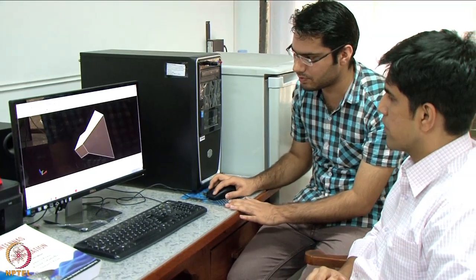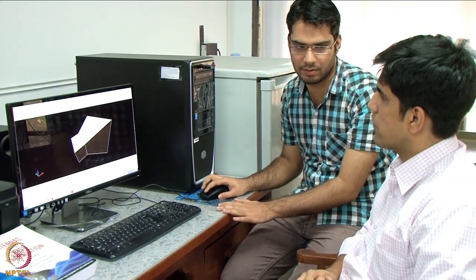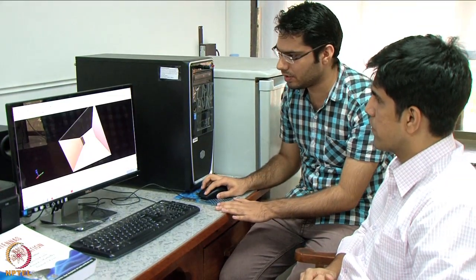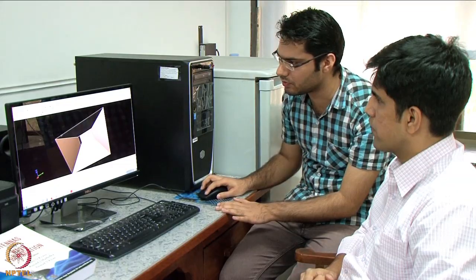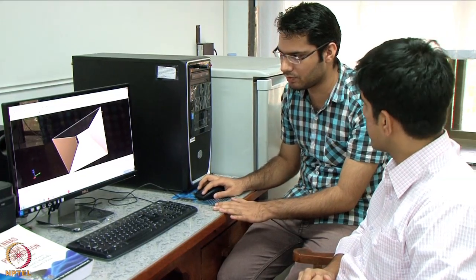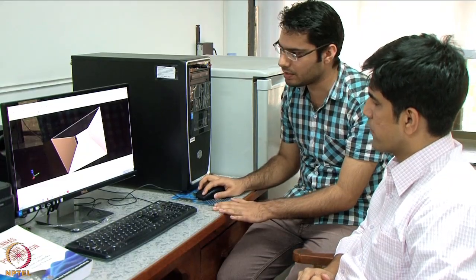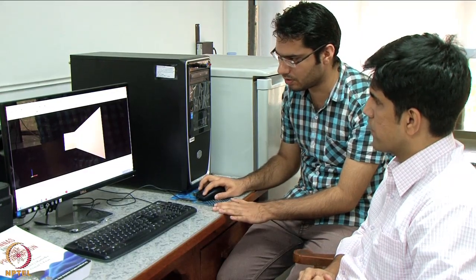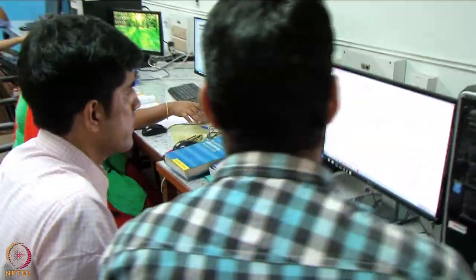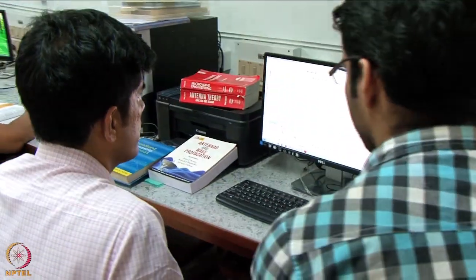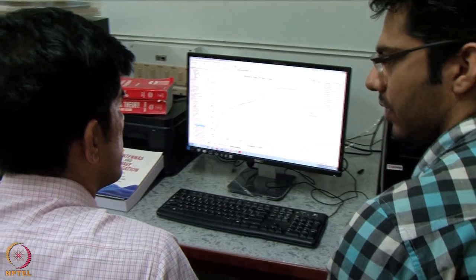The length of this waveguide is optimized to 110 mm. And the flaring we have done: the wider dimension of the aperture is 450 mm, and the narrower aperture is 320 mm. The length of this horn is around 250 mm, and we can see the gain of this antenna is varying from 8.4 dB to around 12.5 dB.